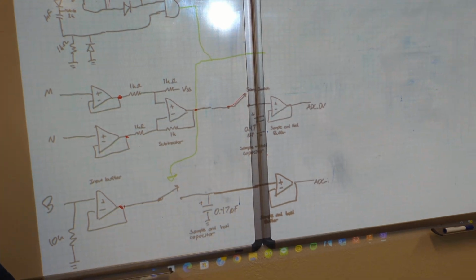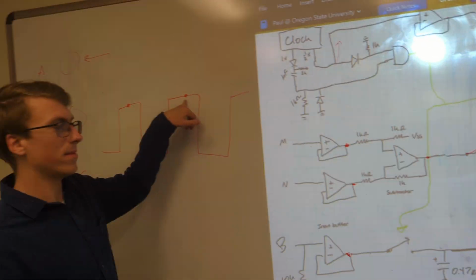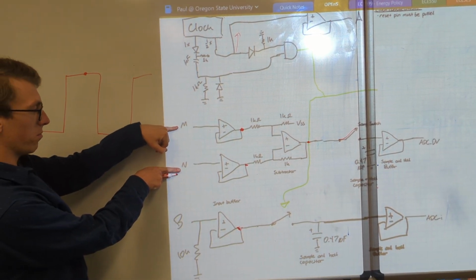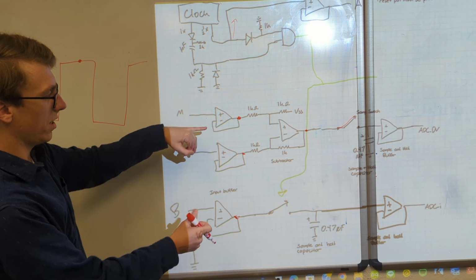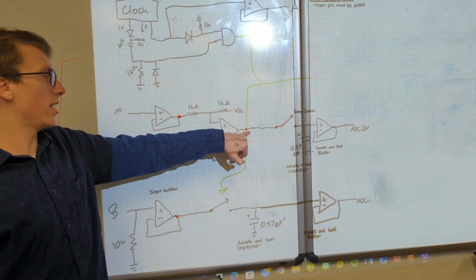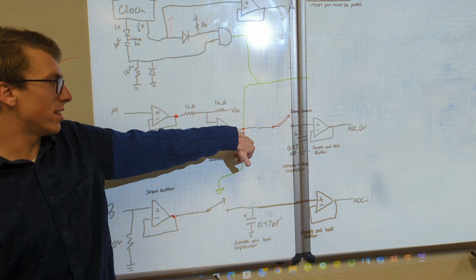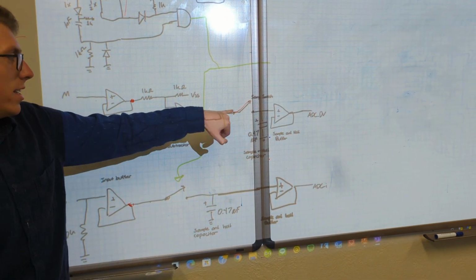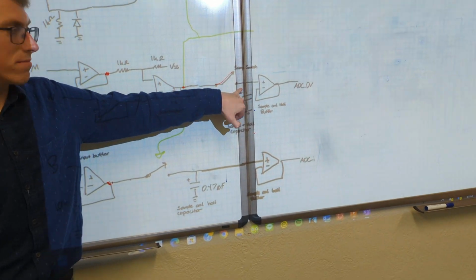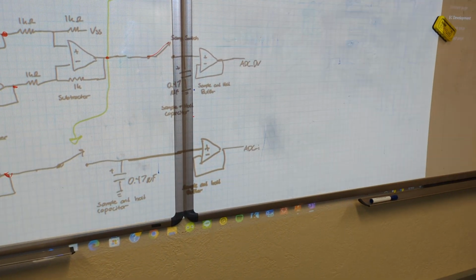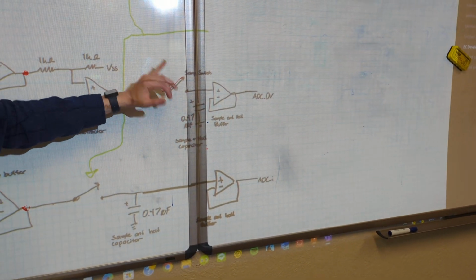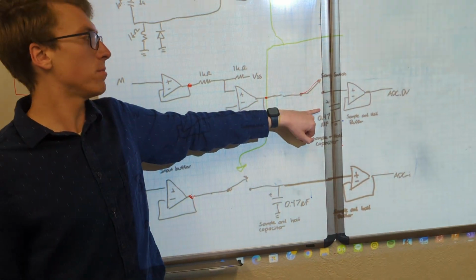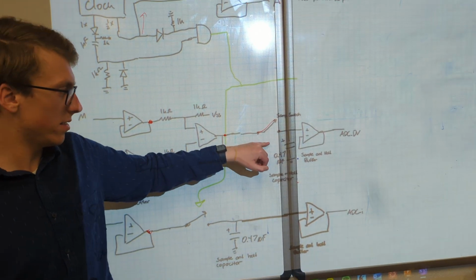It's pretty straightforward, really. At this instant in time, at the peak of my square wave, 2 voltages are induced here by the voltage gradient. They're compared. The difference between them is present on this node. And then at the instant my sample trigger fires, this voltage, the output of my voltage comparator, gets induced across my capacitor. Right here. Afterwards, my switch opens again, and this capacitor is going to retain the voltage that I've injected on it for some amount of time. Related to the value of the capacitor?